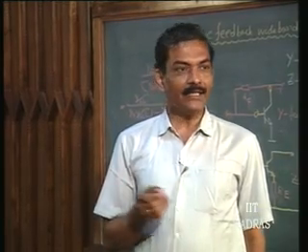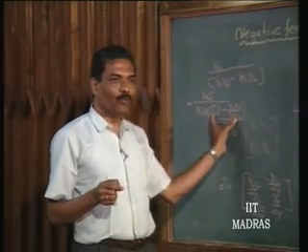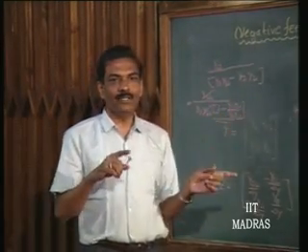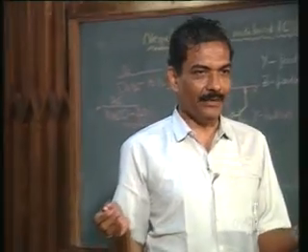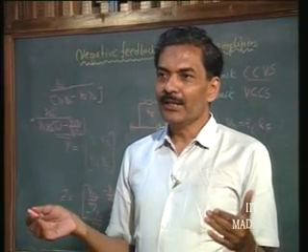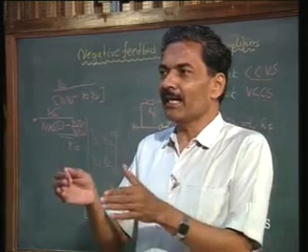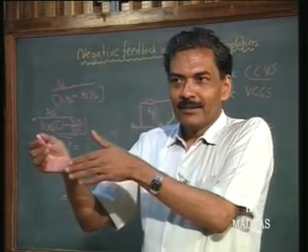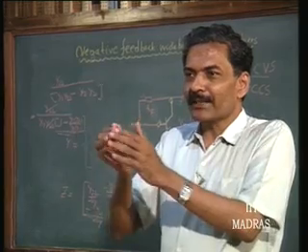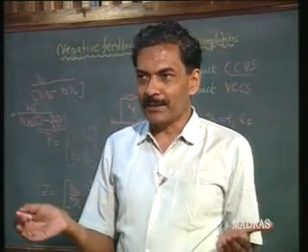Okay. That is getting modified by a factor of 1 minus what is this? y12 y21 by y11 y22 is, by definition, nothing but the loop gain. If you consider this as a voltage amplifier, it will be nothing but A by 1 plus A beta factor. This A and beta factor are applicable only for voltage, whereas in this case it is a general parameter, okay.